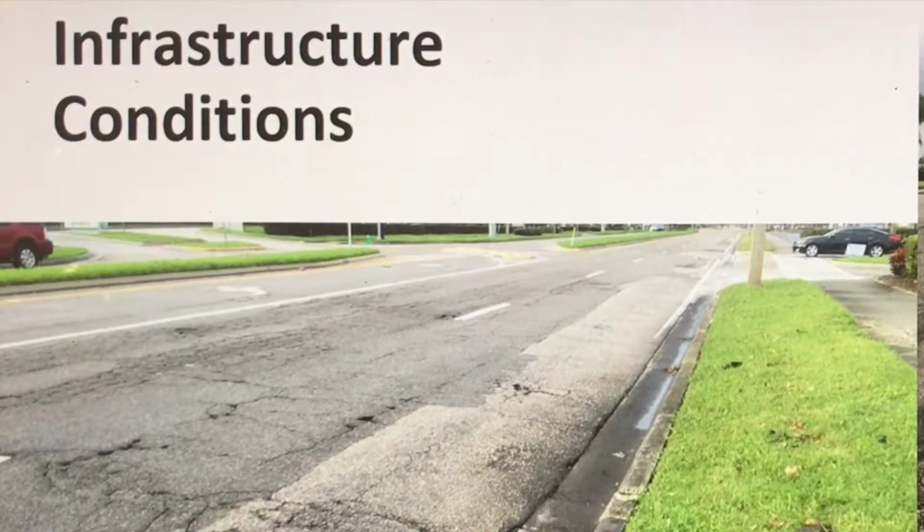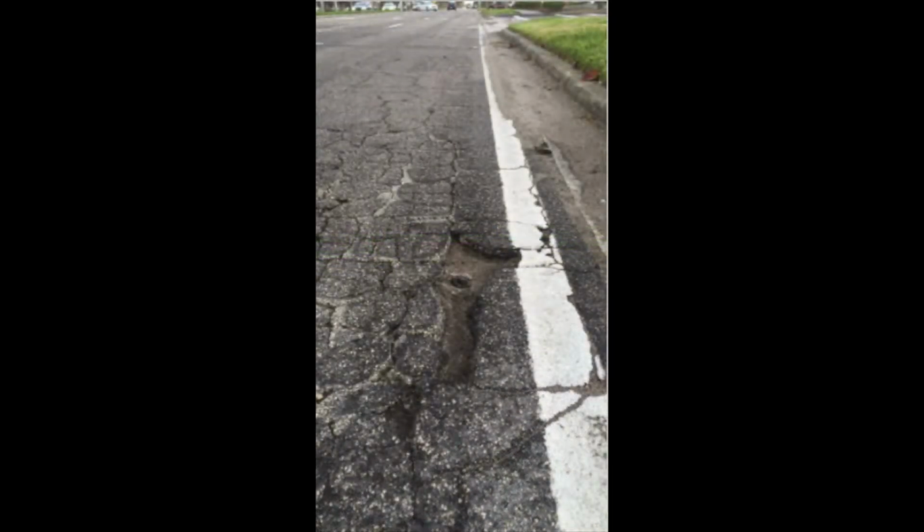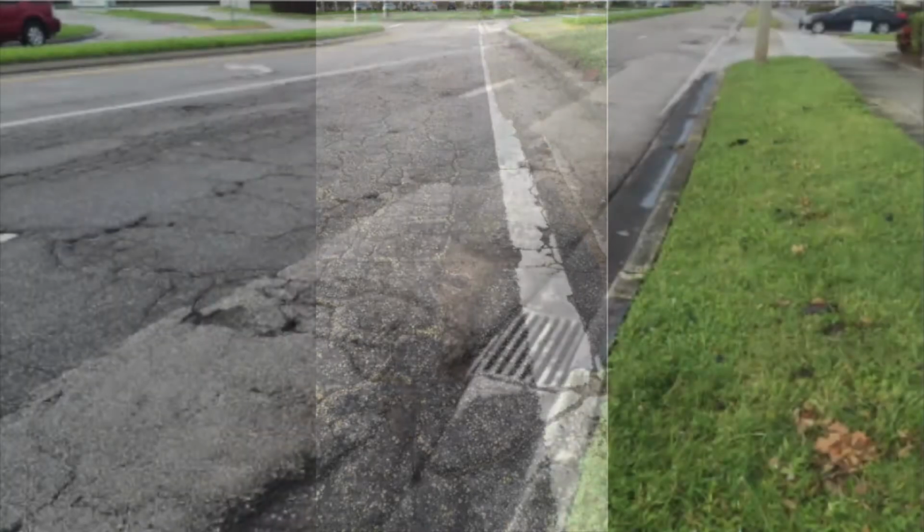The cracks along the roadway could not be quantified due to the extent of their deterioration. It was determined that these cracks existed along the entire 0.24 miles of the South Babcock Road segment. Numerous potholes were identified and determined to be up to 3 feet long by 6 inches wide by 1 inch deep, as seen in the figures.